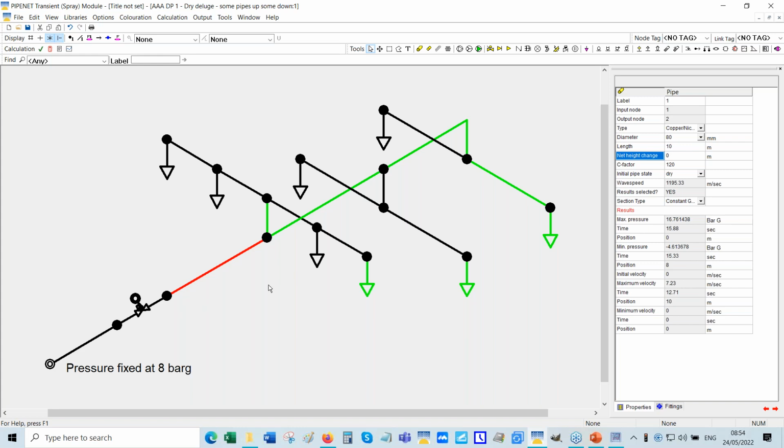Once this pipe gets primed, of course, the deluge system discharged very quickly. You cannot change the position of the deluge system. So the only way you can truly solve it, only two ways I suppose, in either case you would have to move the deluge valve to a higher level.